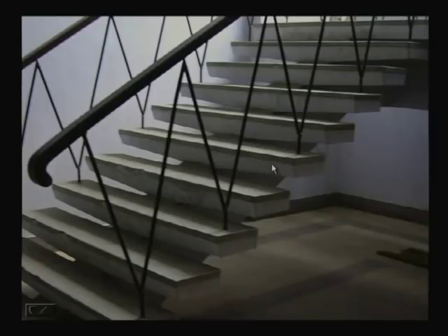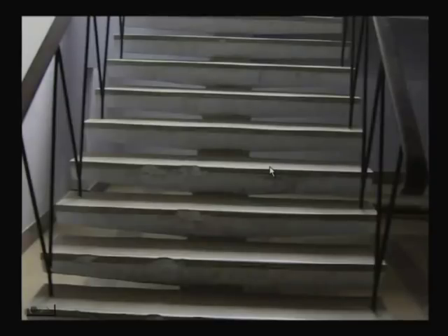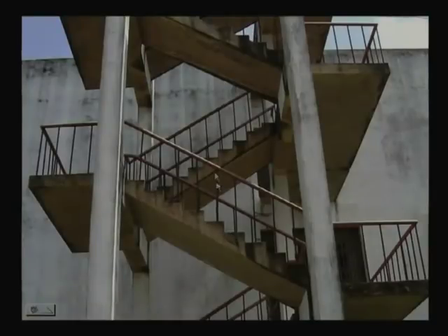So that way you can design, but the most popular one, this is another view, you will find in most cases this type of staircase. This is the most popular one, and we shall design this one, but I shall also tell you how to design other staircases. What you have to do for any staircase is find out what the governing bending moment is, how it is acting, about which axis, and then design according to that, as well as for shear force also.